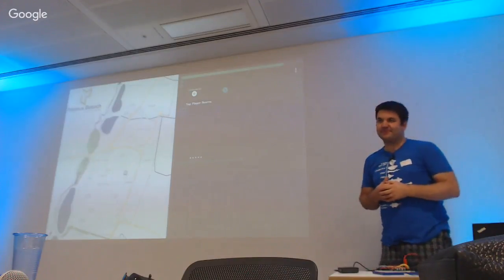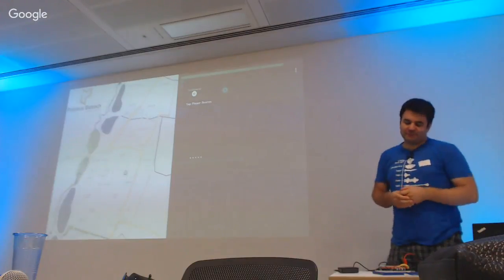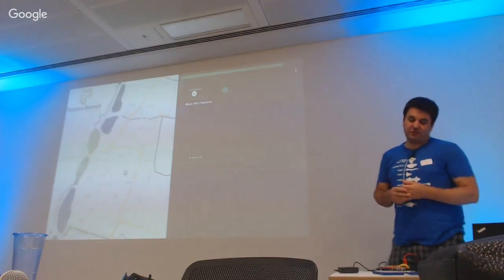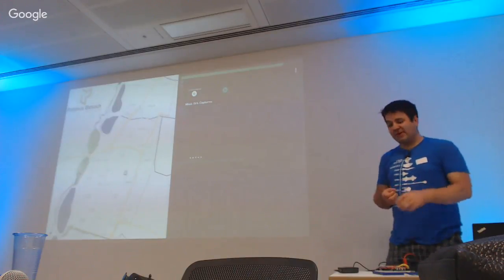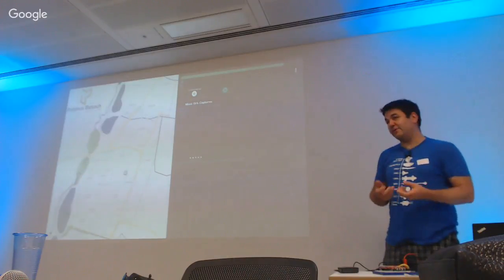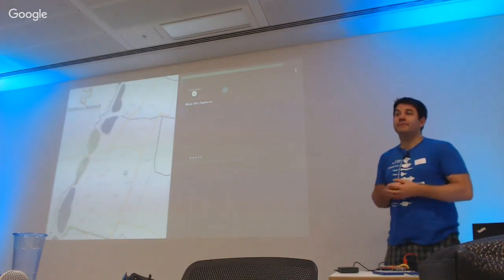I'm wondering, could it be modified to use a micro:bit? I'm just thinking, sort of thing kids could play with a micro:bit. I mean, sure, you could replace the PIC with the micro:bit, but I don't know what the power utilization is. My main reason for the PIC chip is that it can go into very low power mode. So actually the idle power is incredibly low.